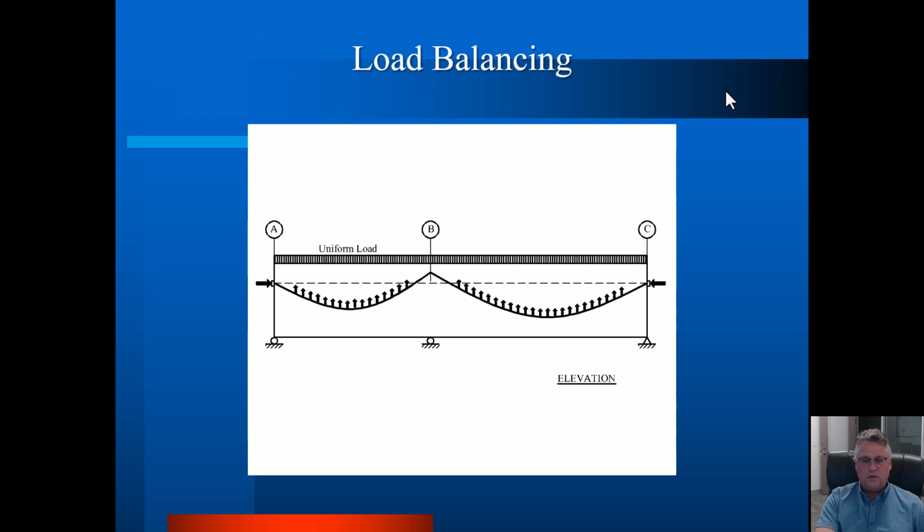Now, some of our load is live load, so it doesn't typically make any sense to balance live load because it's transitory. Most of the time it's probably not there, certainly not at its full value. Dead loads, particularly the dead load of the concrete itself, will always be there. So we are typically talking in terms of balancing a percent of the dead load.